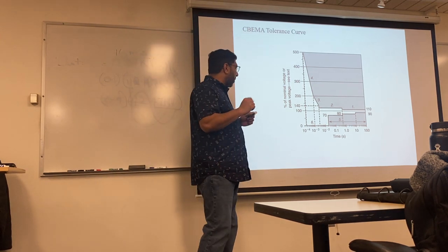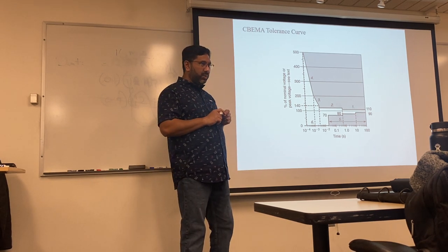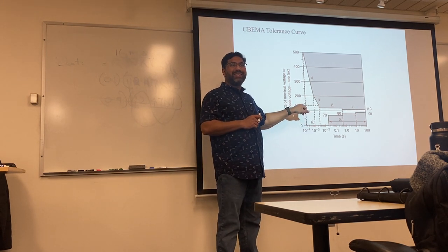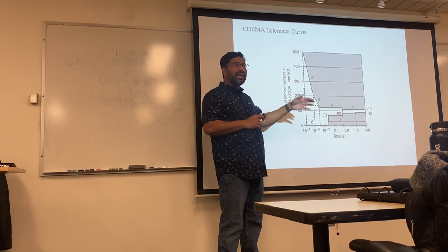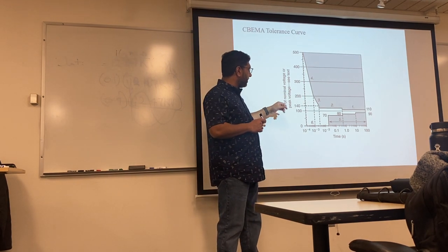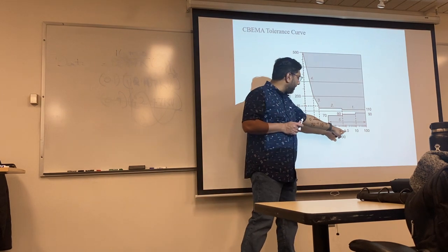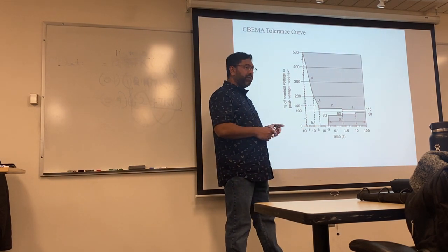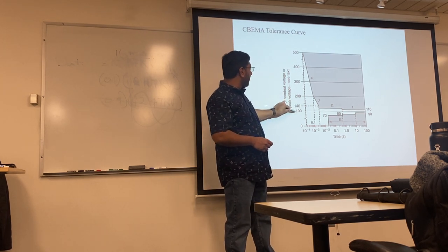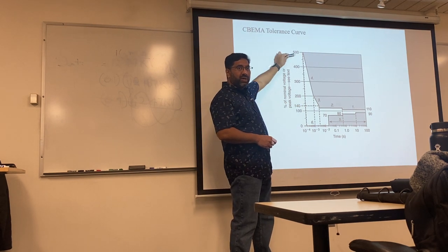What I kept quiet on the other day is the time associated with it. A breaker opens or closes depending on the energy, and energy is I squared T. So not only should I be concerned with my currents or voltages, I should also be concerned with how much time I gave the breaker. If it was very quick, imagine this to be 100, I can go up to 500, so 5 times what I rated for.